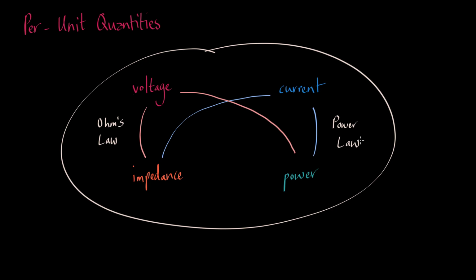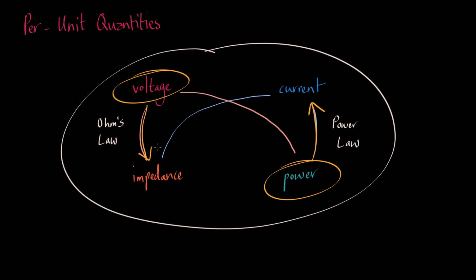Because all the parameters are connected in some way, we can prove quite easily that if we were to set any two, let's say some arbitrary voltage value and some arbitrary apparent power value, we could get a corresponding unique value for each of the rest. What does this mean? For any power circuit, we need only to select a set voltage and a set apparent power, and we have defined the entirety of the base values for that circuit. So we now know there are 2 degrees of freedom when deciding what bases we want to set, and that the 2 standards selected are voltage and apparent power.